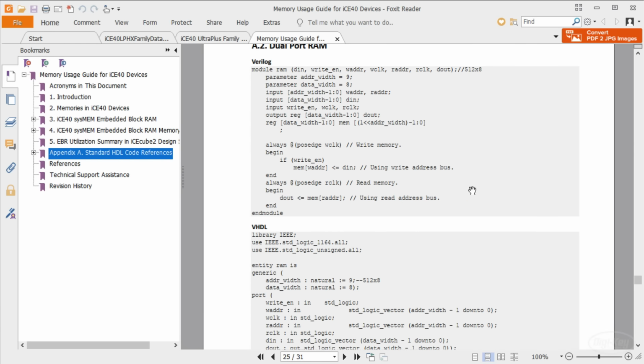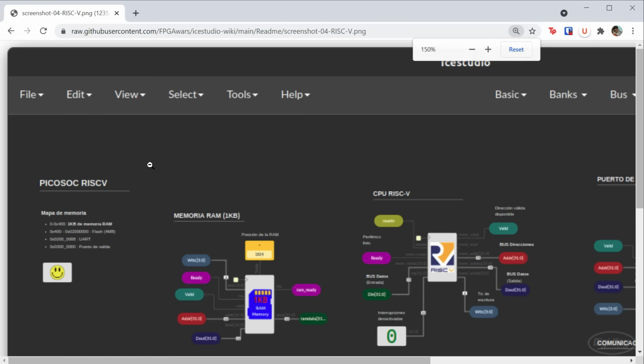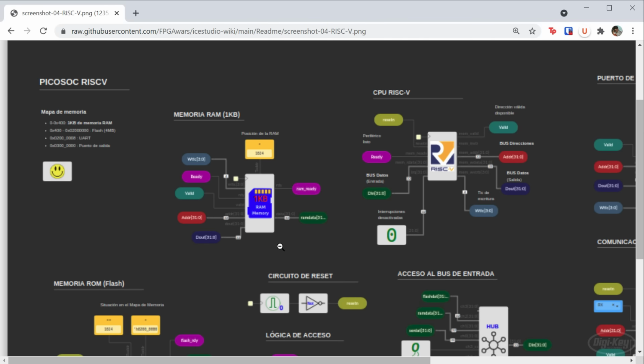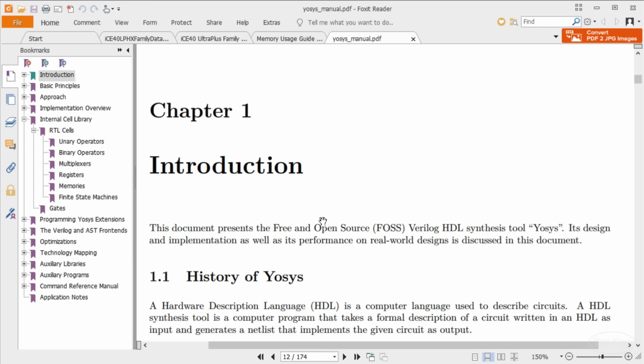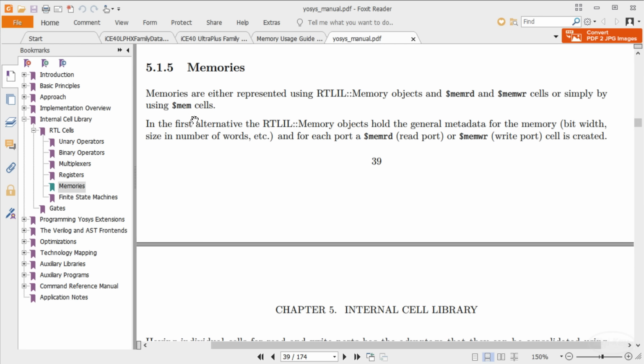If you are using a graphical development environment like iCEcube or Vivado, you can often drag and drop memory elements onto the canvas. You would then configure the element and connect it to other parts of your design. Sometimes your synthesis tool will let you instantiate block memory directly using system functions or tasks. In that case, you would want to follow the instructions for your particular synthesis software. We're going to do something else. We'll write our block memory using plain Verilog and let the synthesis tool infer the block memory from our code. This is more portable, but it means we have to trust the tool to do its job.